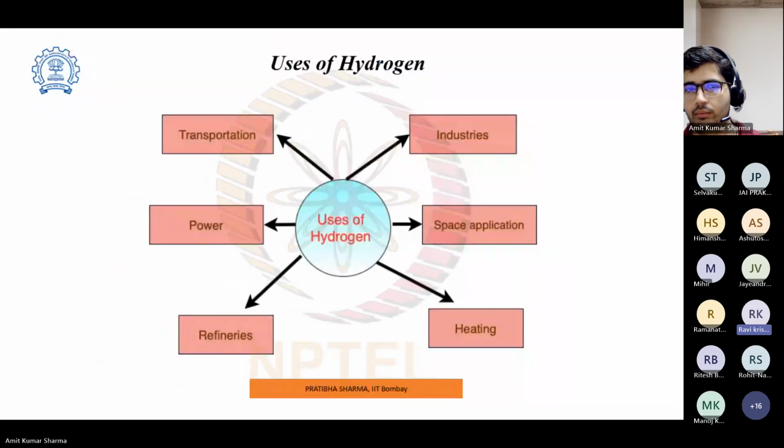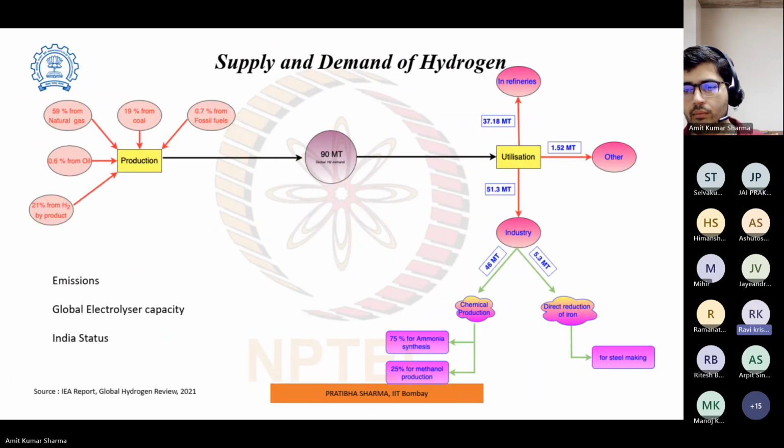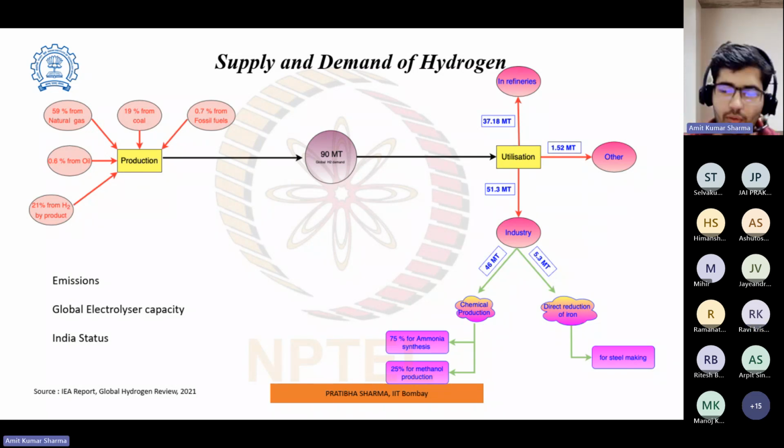Sintering materials are used in blast furnaces for making iron and steel, where they use coal or some other constituent to make the sinter. In the reformer, sintering means that the free carbon fuses together to form the sinter and chokes the reformer tube. Thank you, it's good to know about sintering.